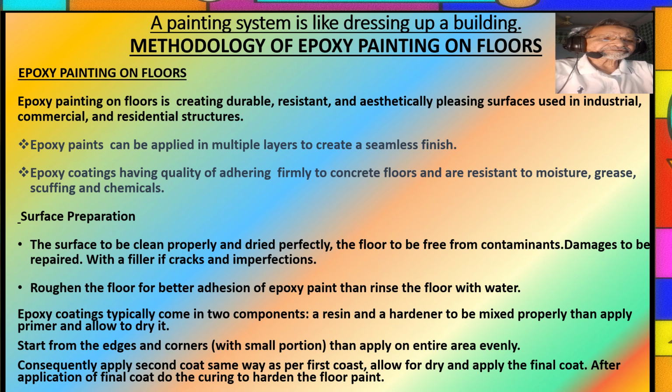Solvent based epoxy works on the same principle as water based, adding extra substances that must evaporate. Adding solvents to the epoxy has a more modest effect on its strength and is also more resistant to the petroleum contaminations in concrete.